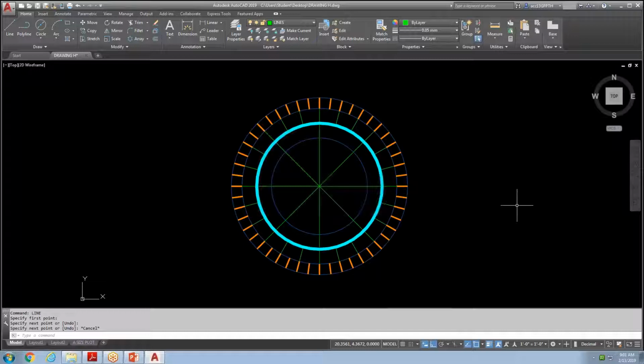And the square, if you look at the very left dimension, it says it's 3 units. The square is 3 units long, and that means it's 3 units wide. So we've got to put those lines in. So let's do that. And we're just going to use an offset command. So we'll start the offset command, which is here. And our first offset, we're going to use 0.5. And we're going to just go ahead and offset this here and here. And you can see how this is working.